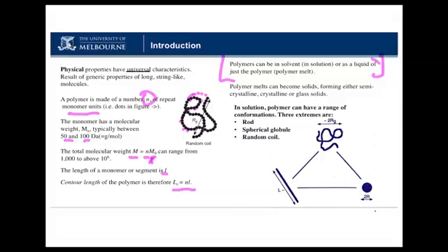Very often they make what are called semi-crystalline solids, where they make sphere-like crystals. Without additives, you can tell a polymer is semi-crystalline or crystalline because it might be opaque. Whereas if they don't crystallize because they're randomly ordered and the chains are all squiggled around each other, they form glassy solids, and those tend to be much more transparent.